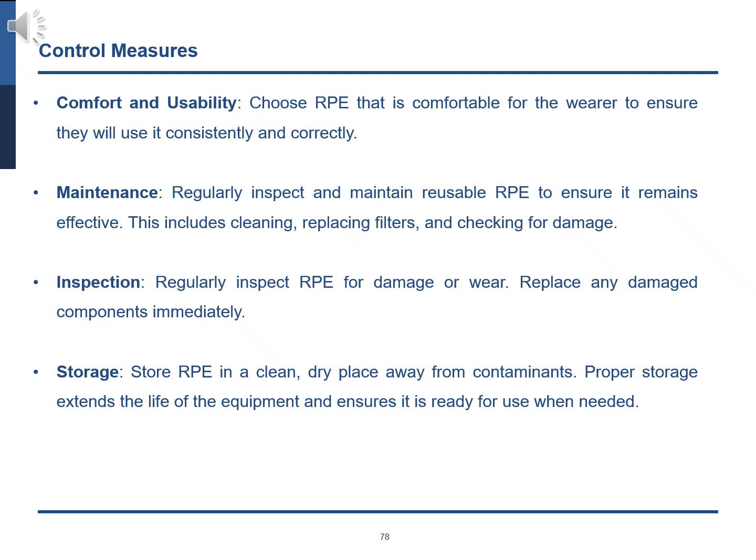Comfort and usability. Choose RPE that is comfortable for the wearer to ensure they will use it consistently and correctly. Maintenance. Regularly inspect and maintain reusable RPE to ensure it remains effective. This includes cleaning, replacing filters, and checking for damage.